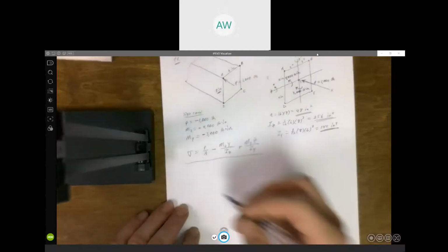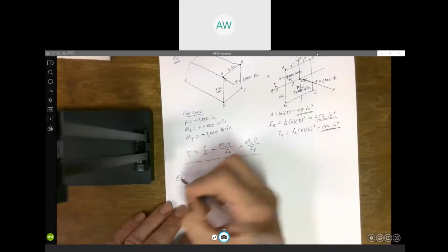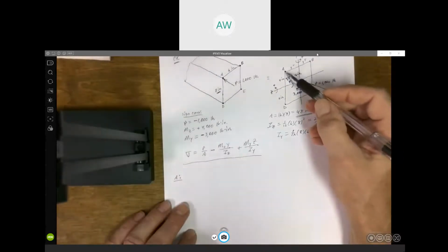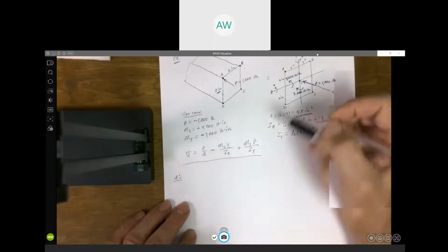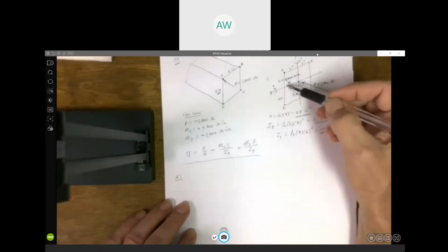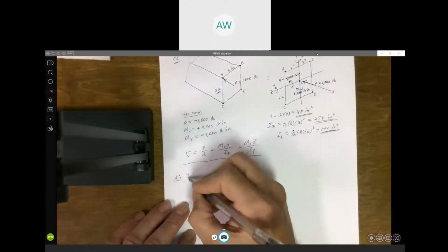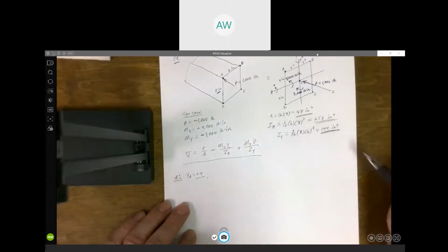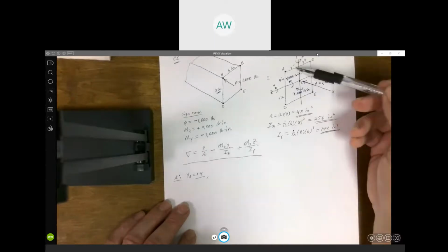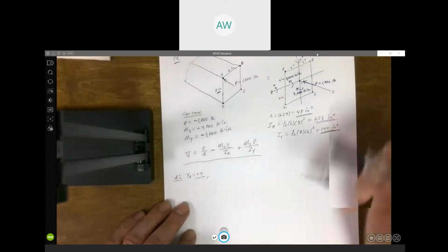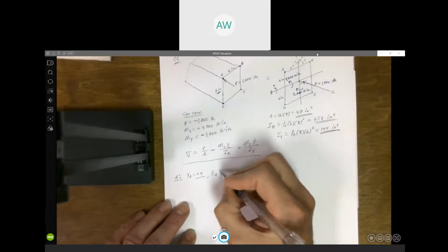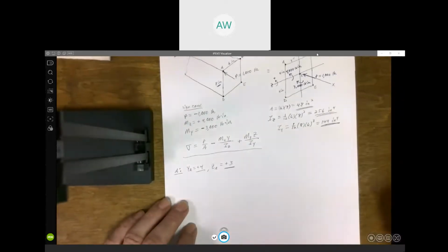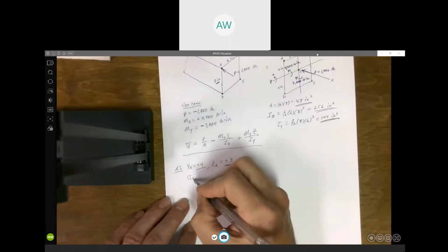So if we want to find the stress at A, for example, again, sticking with our sign convention, here's point A. So y is going to be a positive 4. And the z location for point A, positive z is this way, so it would be a positive 3.